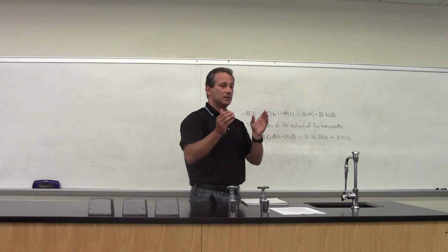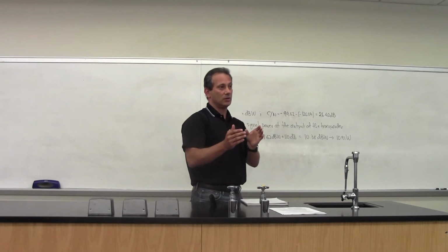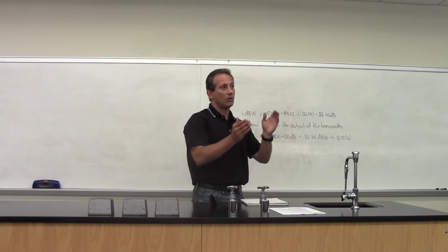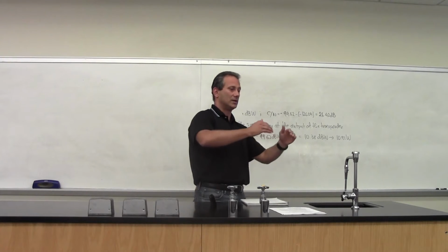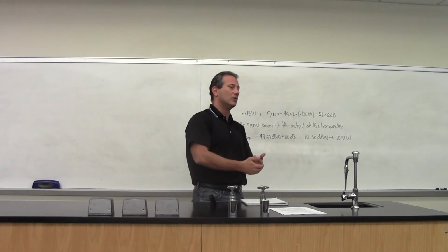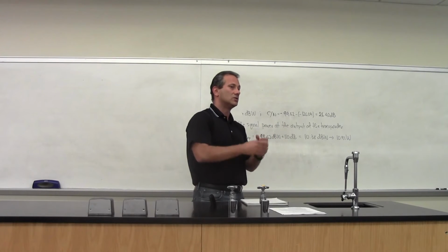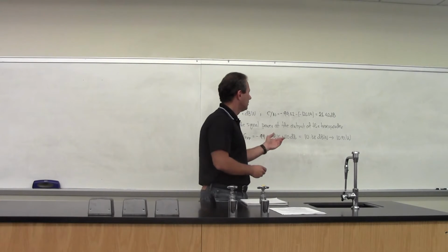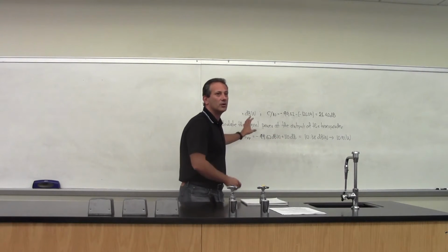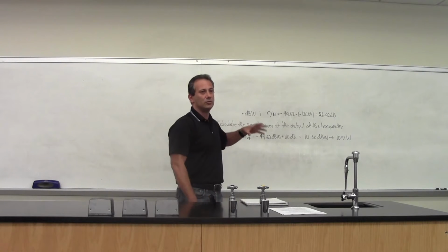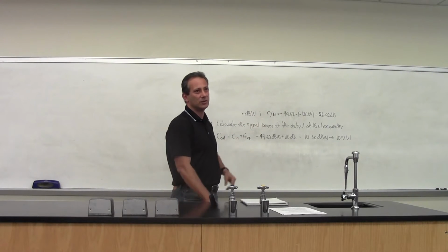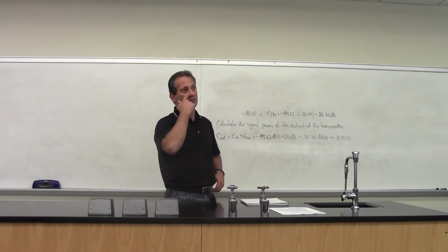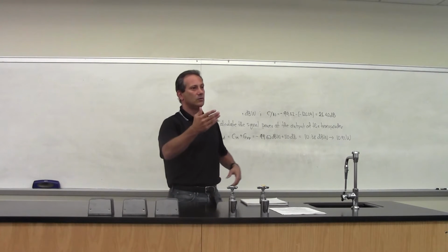Now that is assuming that you are working within the dynamic range of the transponder. Because if you start overdriving the transponder, then you get additional noise from nonlinearities. We are not dealing with that now. If nothing is said, assume that you're in a linear region. But if you're doing problems, be cognizant of that. How do you understand that?